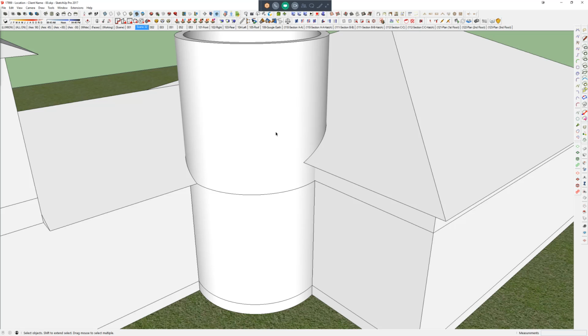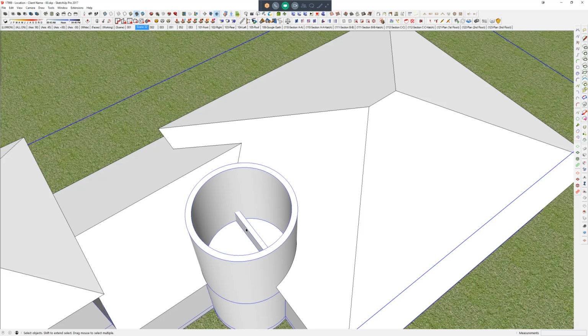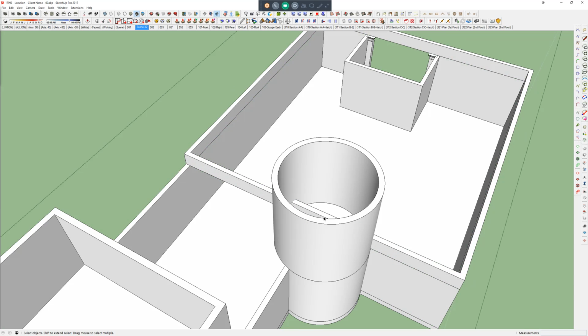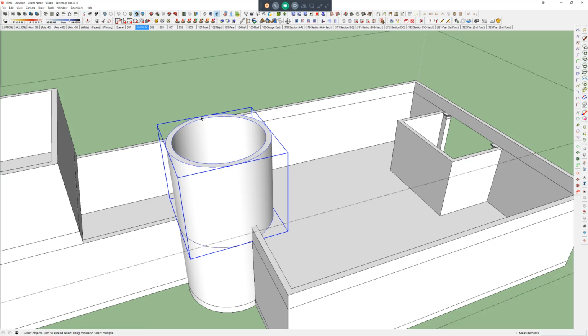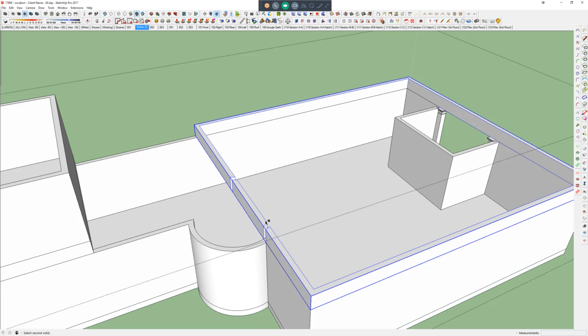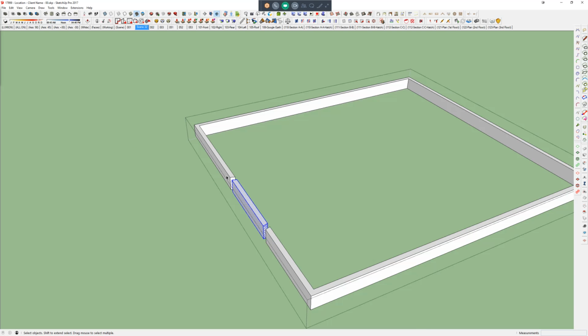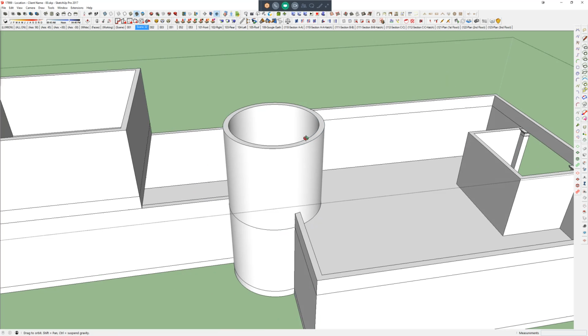I've been using these for a couple of years now, and that's why it's really just become second nature for me. But even this wall here that I'm adding in, I'm going to make a copy of this upper tower. I literally just hit Control C, and just more for you guys to see, I'll do copy. And now I can do subtract from this wall, and I can come in here and just delete out this centerpiece. Now I'm missing my upper tower, but since I copied it, I could just do paste in place, and I put that piece right back in.